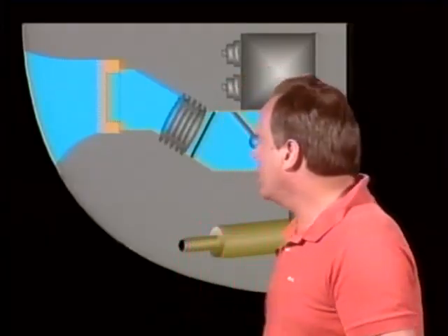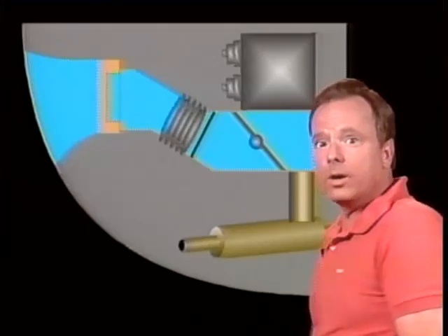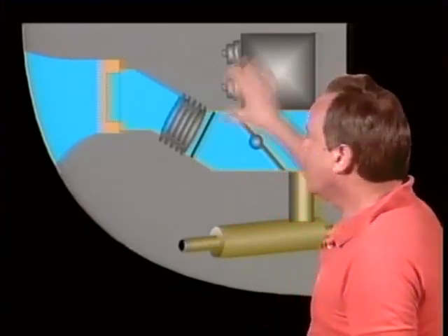Okay, so would you normally use a carburetor heater, preheater they call it, preheat for the carburetor on takeoff? And the answer is no, not unless it's absolutely necessary, because you do have loss of power when you have hot air going into the engine. The reason for that is the air is less dense. Also, the mixture gets a little richer because the air is less, the fuel stays the same, so the mixture gets richer. So a carburetor preheater is not generally used on takeoff.